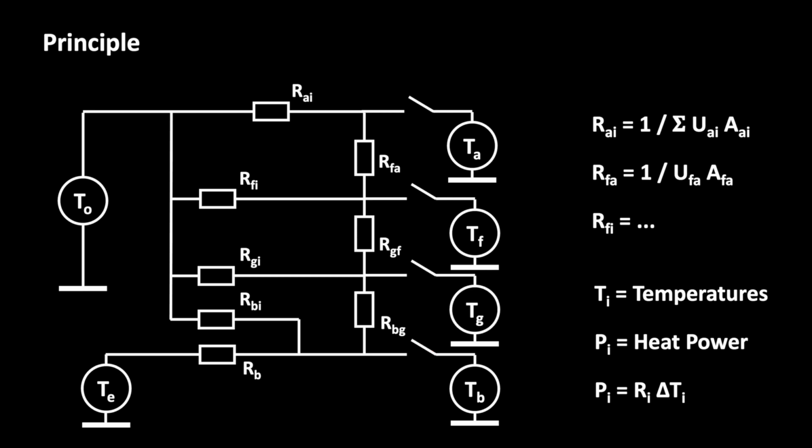This will either enforce the temperature we set on the thermostat, or, if the heating is off, we get the temperature resulting from the heat flows from the adjacent rooms. For the switches, we use the resistance 0 for closed switches, and for open switches we use the value 1000 for the simulation calculation.